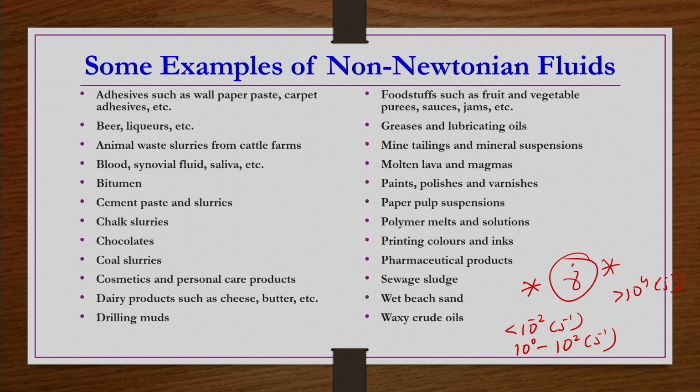So, these ratios, if they are in the small range, then it is possible that the material may be Newtonian. So, you do not need to worry about the characteristics of non-Newtonian behavior, their model, their influence on the performance of the processing unit. You do not need to consider that, even though the material may have non-Newtonian characteristics at some other, different shear rate.